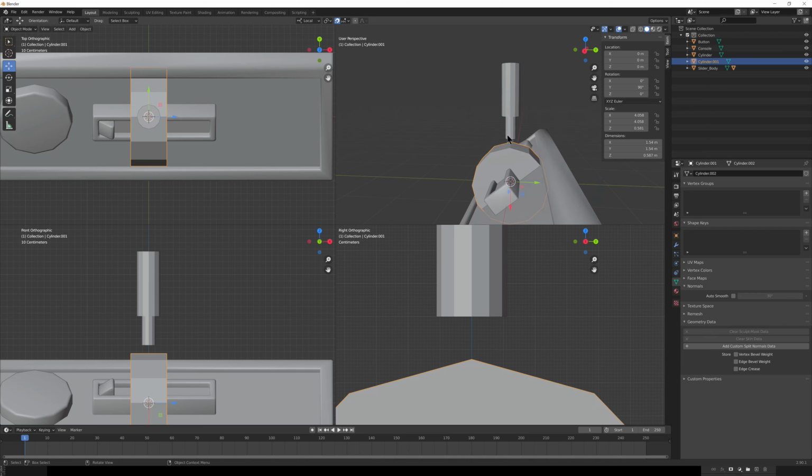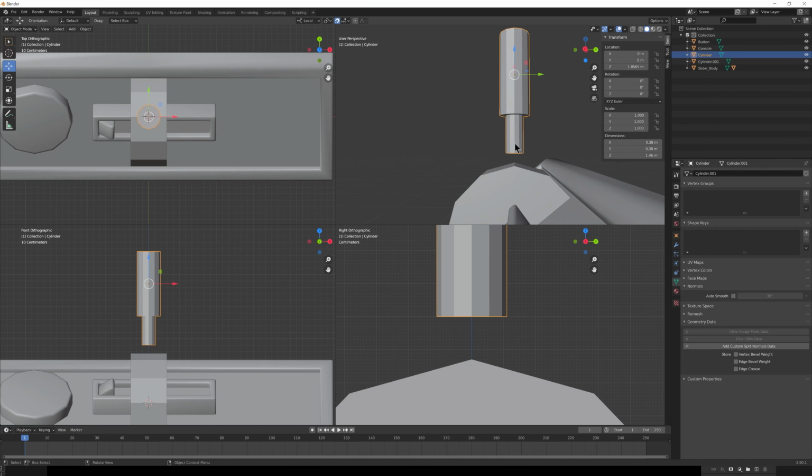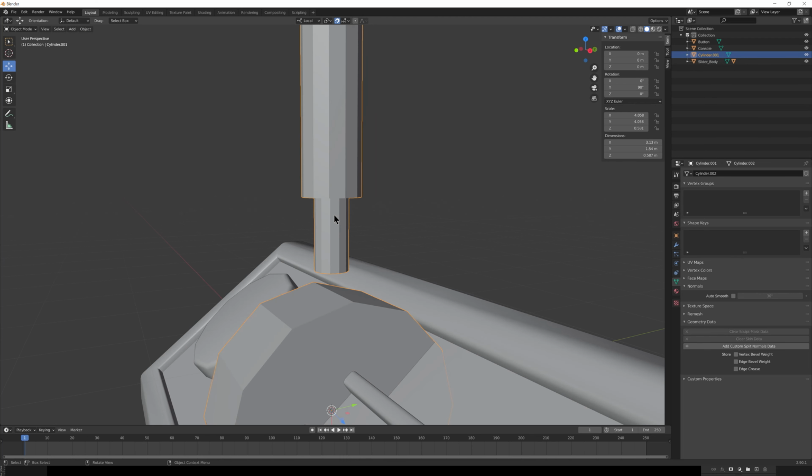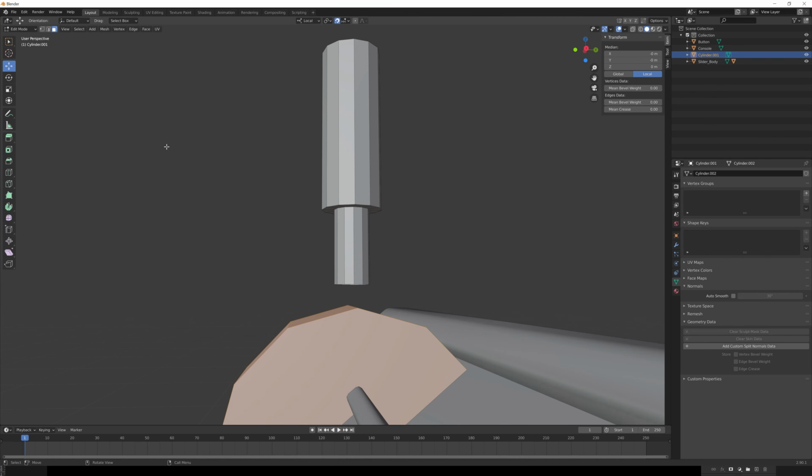This piece and this piece need to be joined. So let's go ahead and get these a little bit closer to each other. Grab both of them, and I'm going to hit Control Alt Q, and let's start by joining them, and then we'll manipulate them after. Go ahead and hit join, and now they're part of the same mesh. Hit Tab to go back to edit this object.